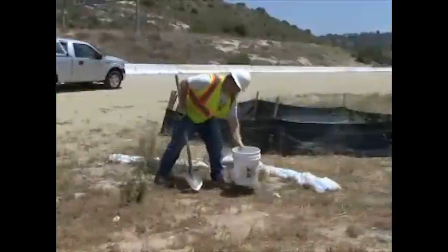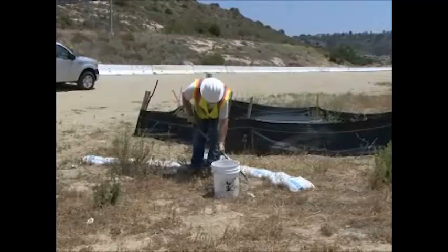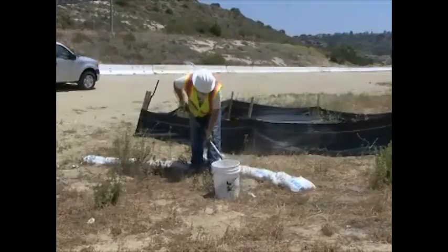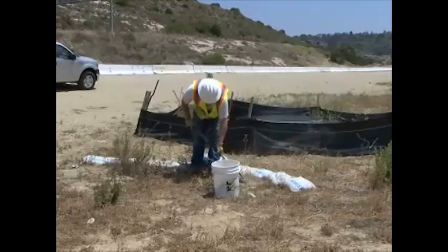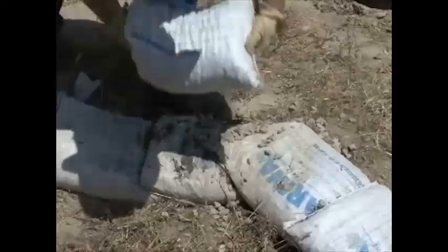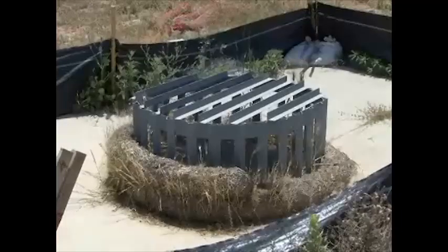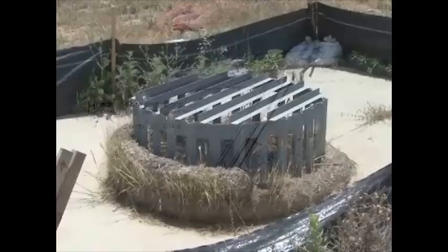Remove sediment deposits when the deposit is 1/3 the height of the gravel bag barrier or 1/2 the height of the spillway, whichever is less. Replace gravel-filled bags when the bag material ruptures or when the binding fails. Repair or replace split, torn, unraveling, sagging, or slumping fiber rolls.